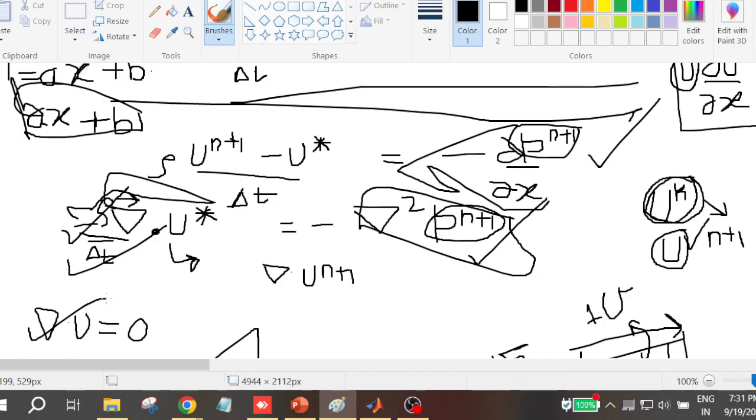In the lecture it was told that if there is no diffusion, the Peclet number will go to zero. I think infinity, no? Yes, it should be infinite, because you have very high convection. If you do not have convection, then the Peclet number is 0, because it determines how strong your convection is.